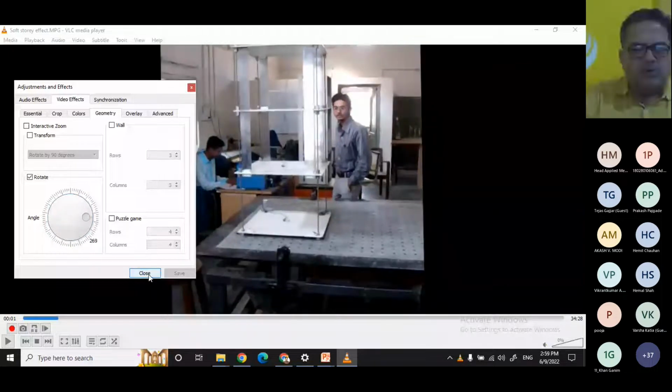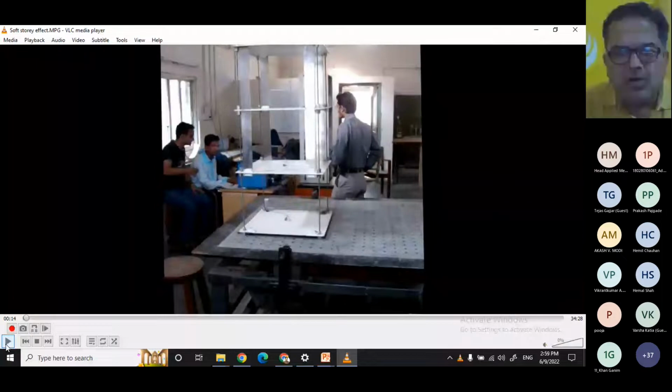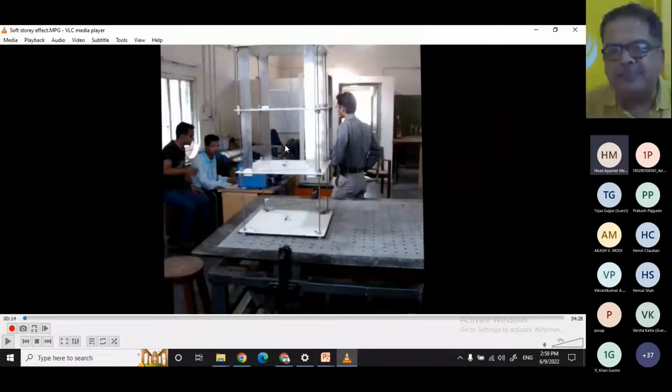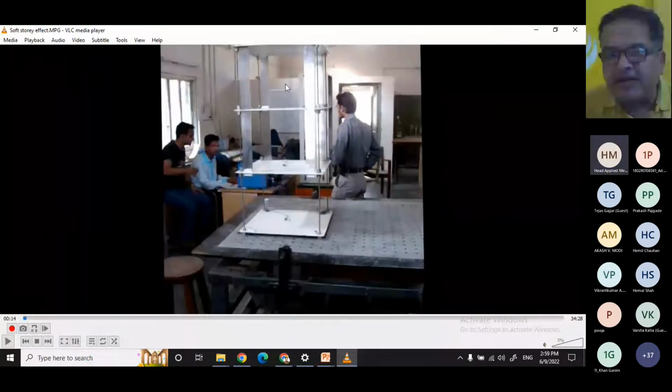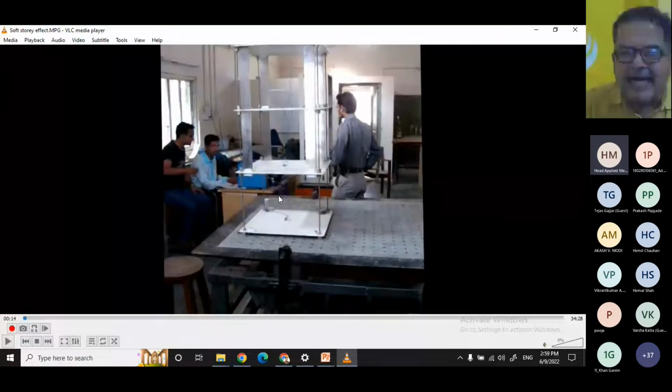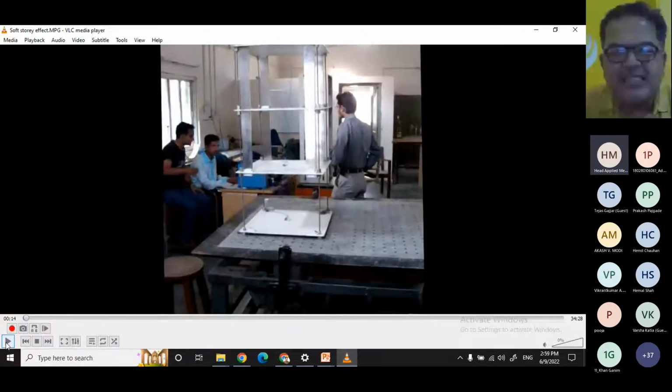Okay, now you can see here on the upper story we are putting the shear walls. These are the steel plates. There are columns throughout, right? It is columns throughout, plus on the first story and second story we are placing the shear wall, but on the ground story we are not placing the shear wall. So there is a stiffness difference. The stiffness of the ground story is less as compared to the first story. But the stiffness of the first story and stiffness of the second story, there is no difference. So you don't have the soft story there. So you have a soft story at the ground story level. That's all, right? Then we'll see how your structure is going to behave.